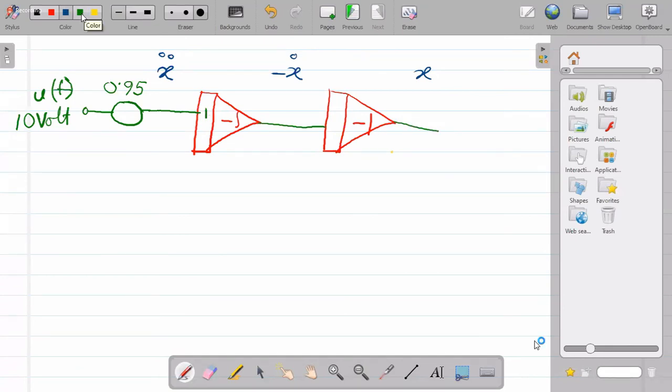Next, you have the signal minus x dot. That is to be fed back over here with a gain 0.8. So here a negative should be given, sir. Sure. Think about it. Any other opinion?